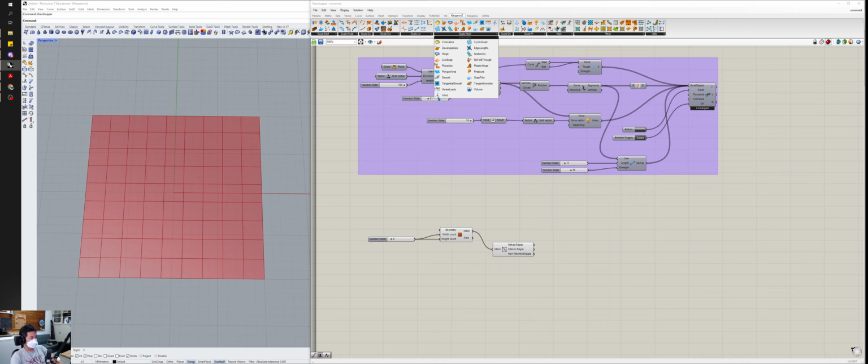Because we're working with a mesh this time, let's go with our edge lengths force, which is similar to our spring force, except that it works with mesh geometry. So we can straight away link our mesh to that mesh force. And you can see here there's a length factor and a strength, very similar to what we had with our spring force.